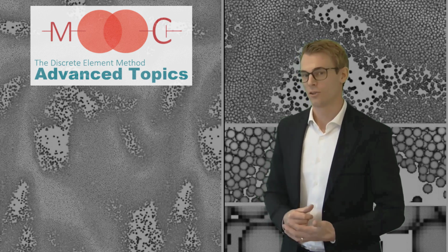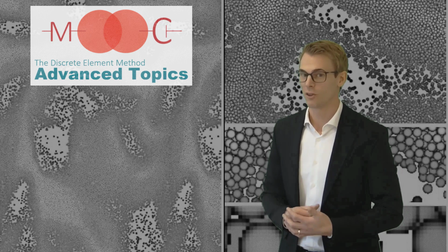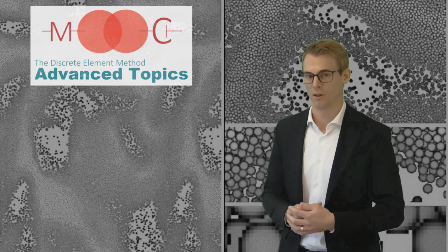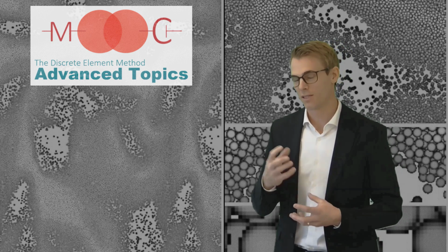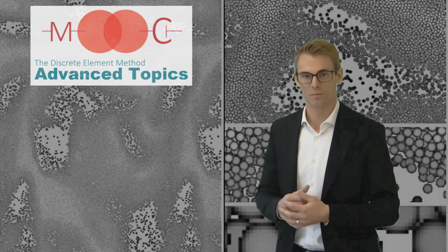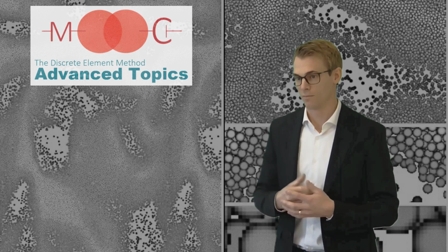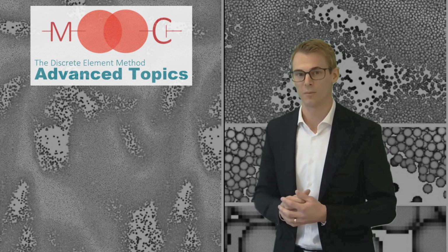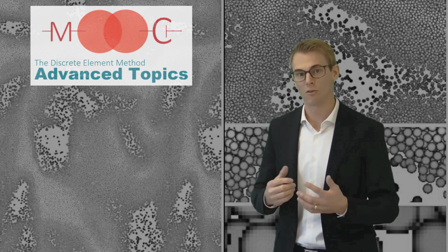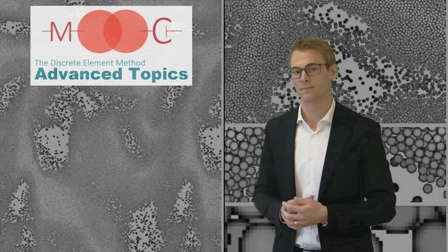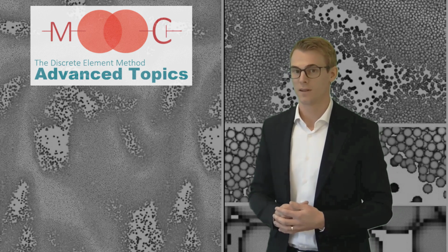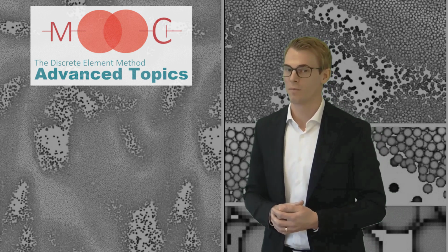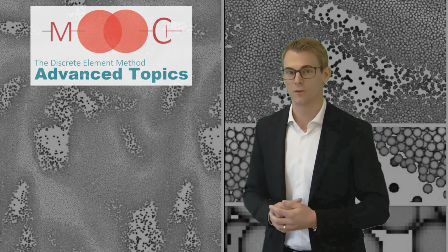Ultimately, structuring a certain bonded particle model in a DEM environment should not be ignored either, referring to the actual setting up of a given bonded particle model, meaning placing the particles and the bonds in space to get a certain bonded particle model, either in a rectangular or a regular arrangement, such as for belt conveyors, for example, or also with a specific randomness, for example, to set up raw materials, mineral raw materials, as in the raw materials sector. Set randomness also means to define a certain distribution in the properties of the particles and the bonds with which a bonded particle model is made of, which could be very beneficial for the overall structure.